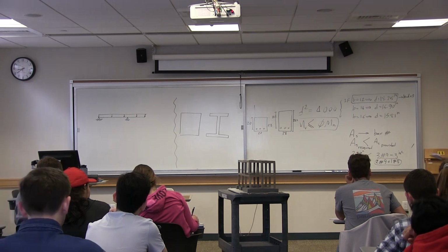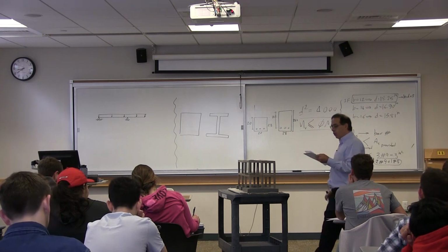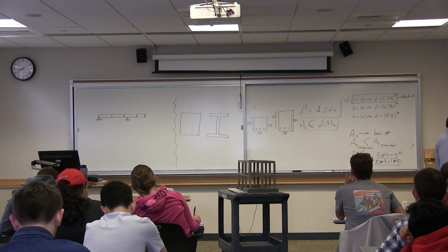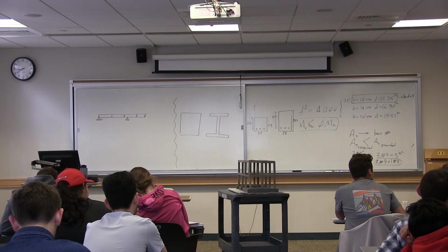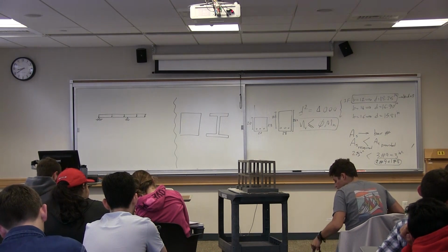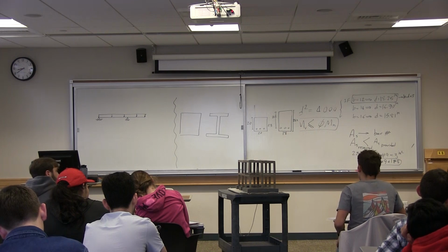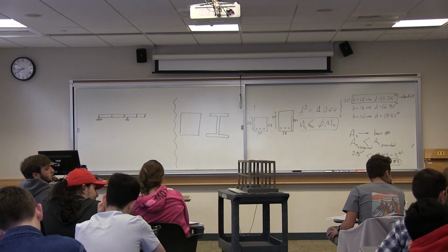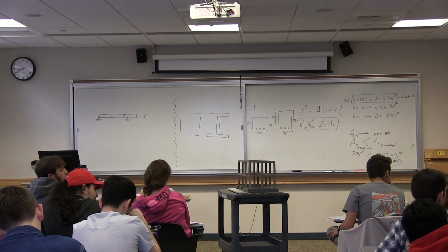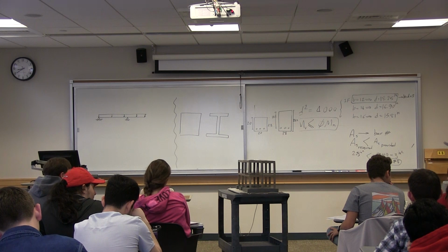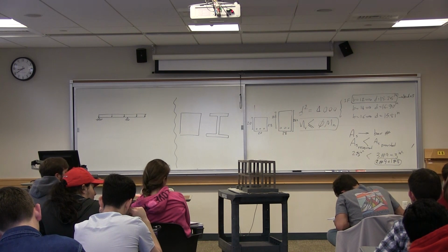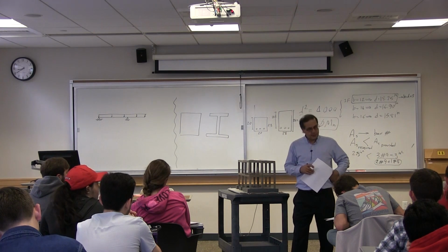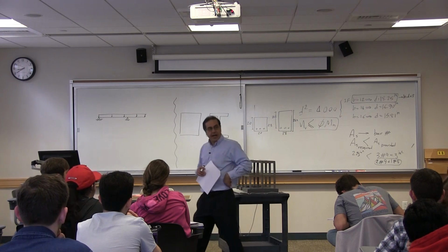It says, select beam size for the largest moment, positive or negative, and then select the steel requirements for maximum positive and negative moment. Finally, sketch the beam and show approximate bar locations. So once we determine the cross-section, do we treat them as 2 different cross-sections, basically? They'll have the same cross-section, but they will have different rebars.